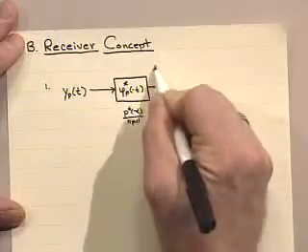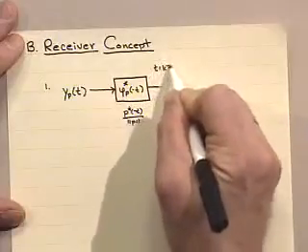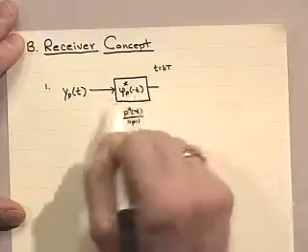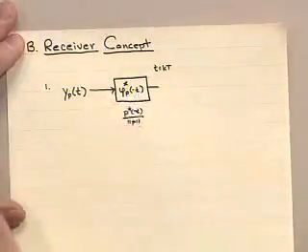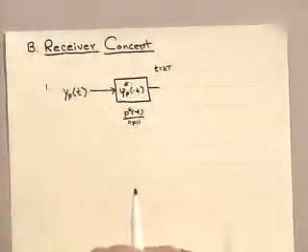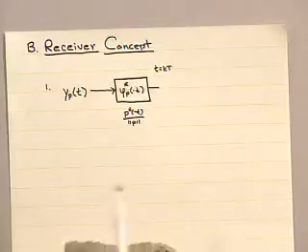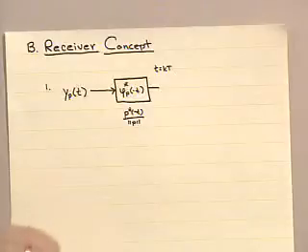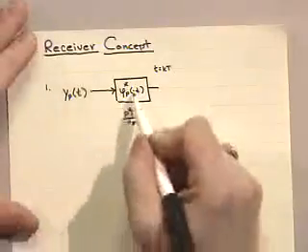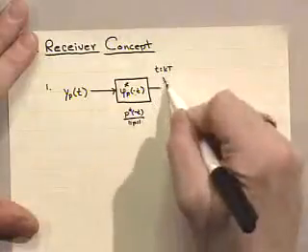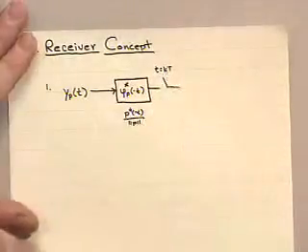And then we would sample at all the right times. And instead of writing capital T minus t and realizing I'm sending successive messages, I realize that the actual filter is p star of minus t. That T or 2T or 3T that I was adding is just a phase difference. Okay. You take the Fourier transform, you just see there's an e to the minus j term that's dependent on what you offset the time argument of the filter. So we get that corresponding time offset just by sampling at all the symbol periods.